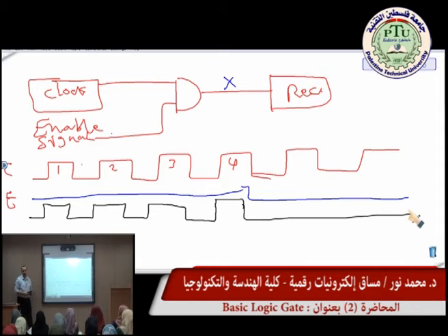It differs from question to question, of course. If it were 2 or 3, the calculation would differ. The period stays the same, but the time interval will differ. For example, with 1 megahertz, the period is 1 microsecond, right? If we have 2 megahertz, we have half a microsecond, and so on. But as far as the number of cycles, if I say I need to deliver this signal for 4 periods or 5 periods, then the question changes, so we take it up to here for 5 periods, or just 2 periods. Or I could say I need to deliver 2 periods, suppress it for another 2 periods, and enable it again for, let's say, the 6th one. But the principle is clear.